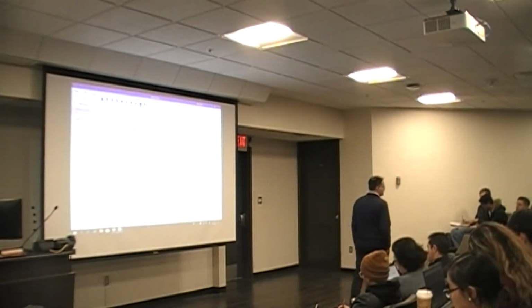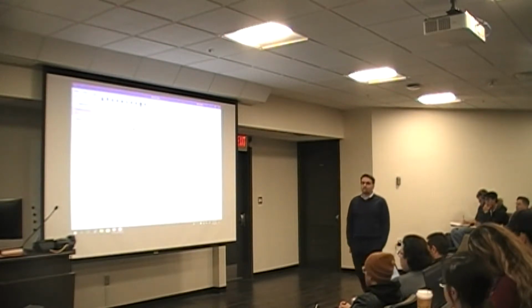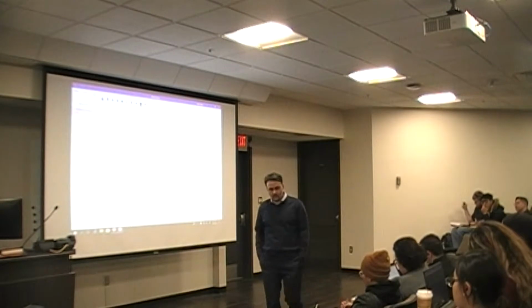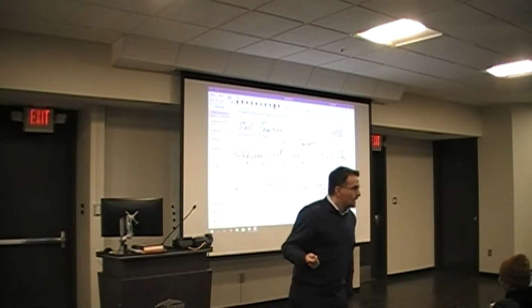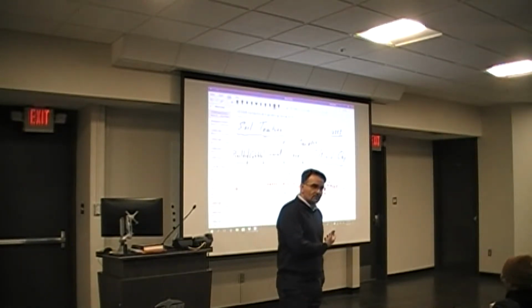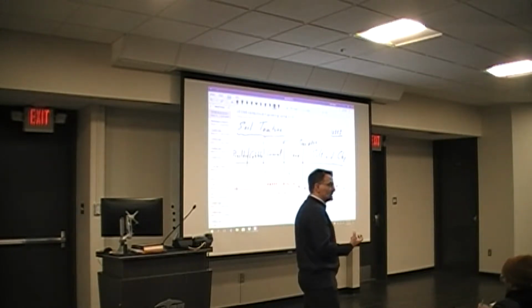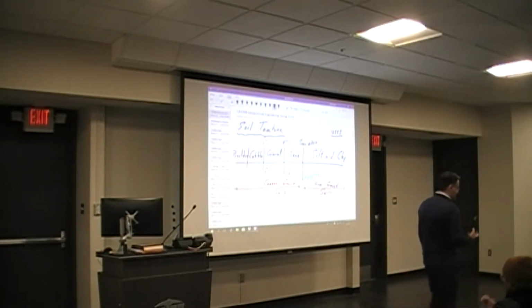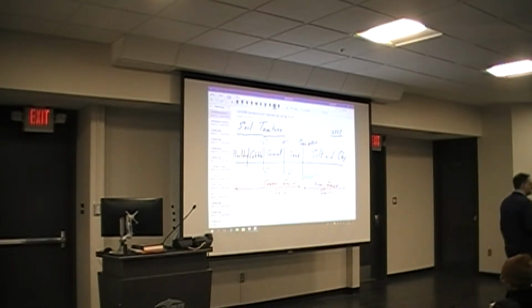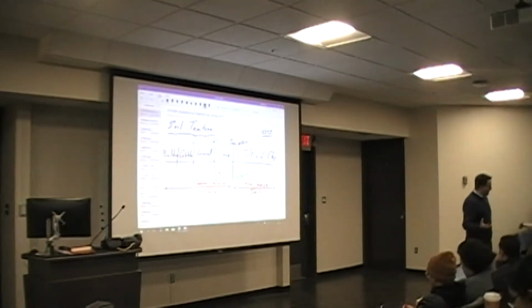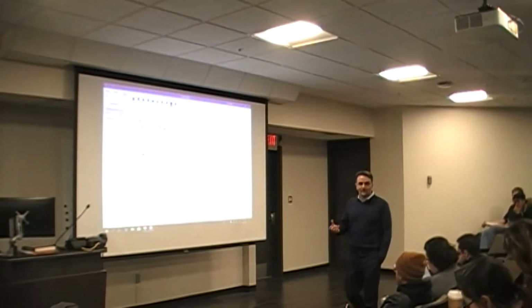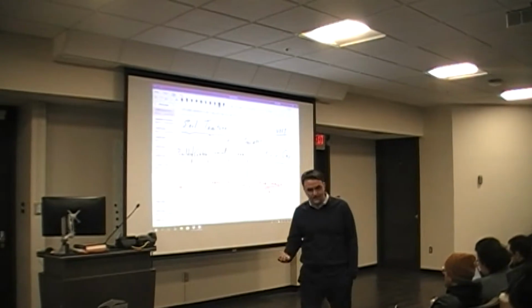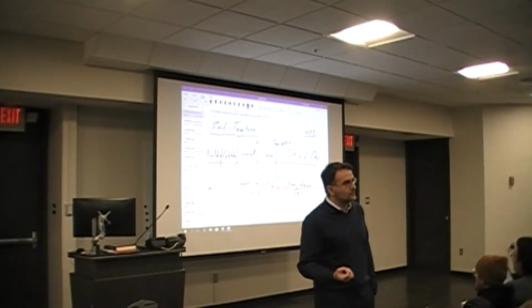Now let's think about the mixture. Remember, we are looking at coarse-grained soils and fine-grained soils. What's the definition of fine-grained soils again from your materials class? You know that these are going to be material that are smaller than 75 microns. But typically, we are looking at it as percentages. So if you have a soil mix where more than 50% of it is smaller than 75 micron, we call that fine-grained soil.